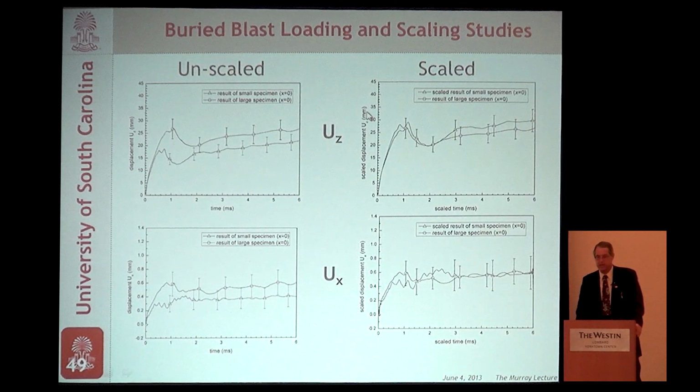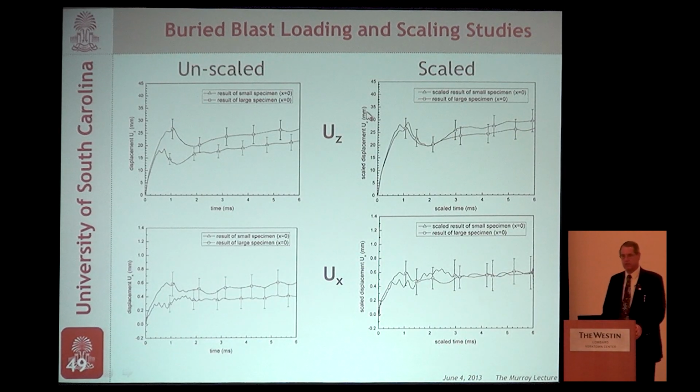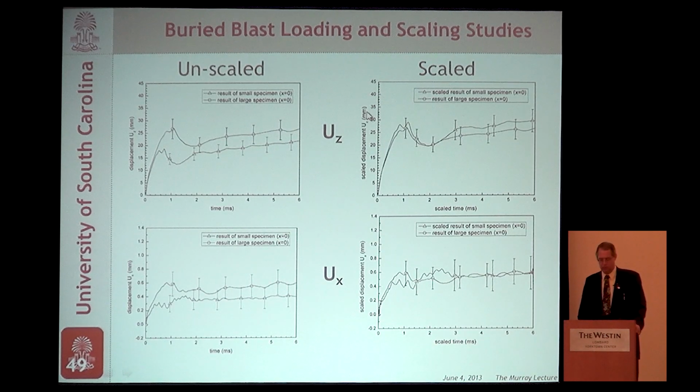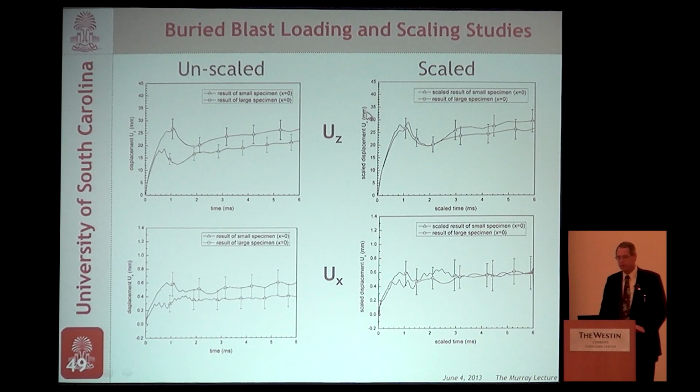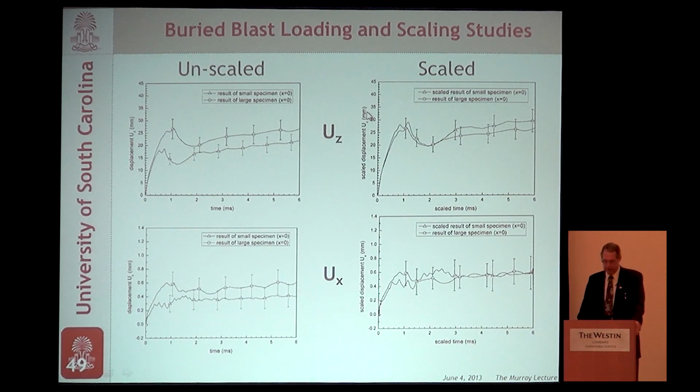We used this to ask whether or not we could scale this. Scaling can be used to take the data from the one test and convert it to the same result as the other one. So we use the unscaled data on the left for the out-of-plane displacement UZ, and on the right you see how we got with 3 tests, and it matched very, very well for both UZ and UX. It's well within the scatter band.